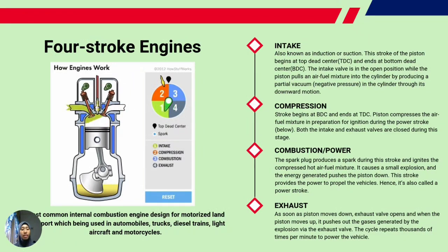The Otto cycle is the ideal cycle of the spark ignition internal combustion reciprocating engines, and it consists of four internal reversible processes. For a four-stroke cycle, one complete cycle equals four strokes, which is 2 revolutions.